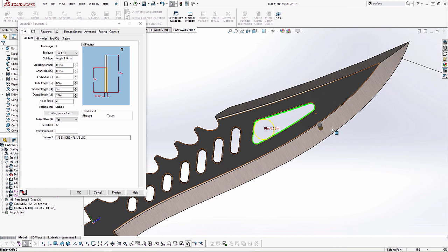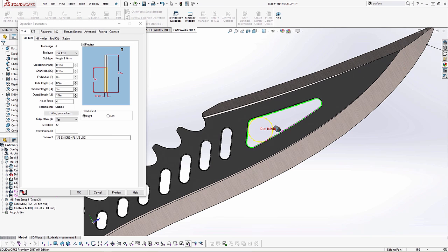If you imagine a pocket with many islands inside of it, or say like an O-ring groove modeled as a pocket, the tool would never fit. So now this is a more efficient and actually more intelligent way of selecting tools. Largest inside radius. Largest inscribed circle.